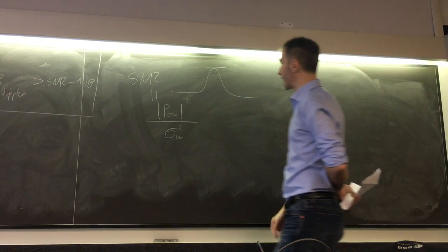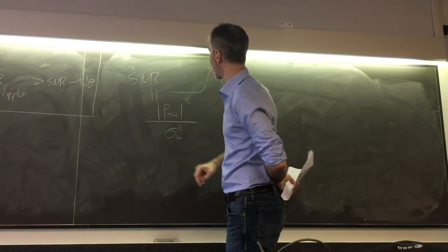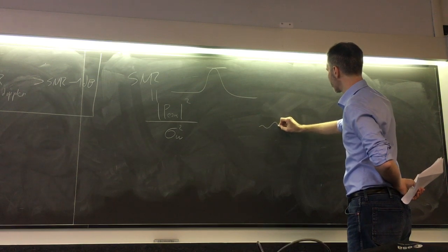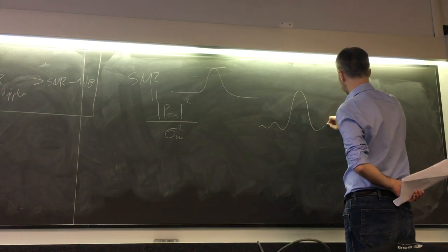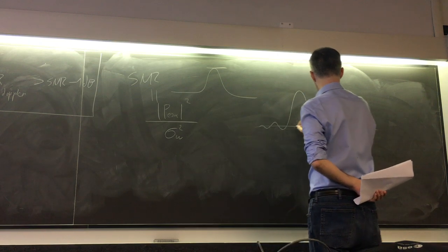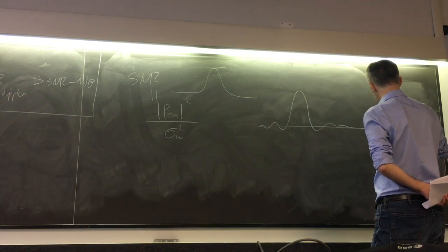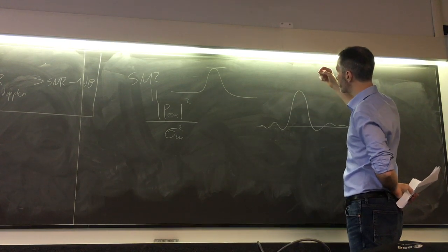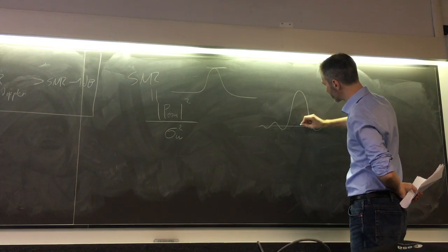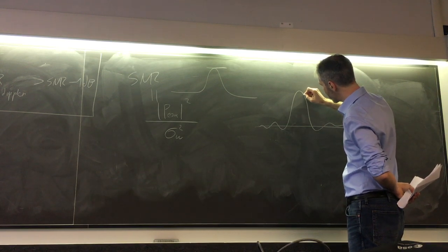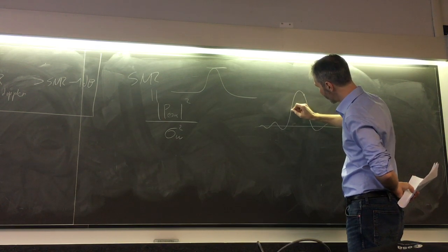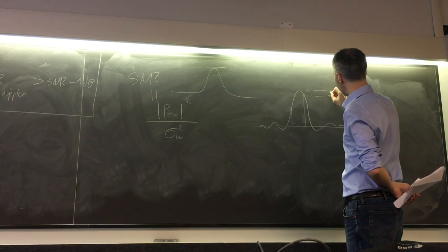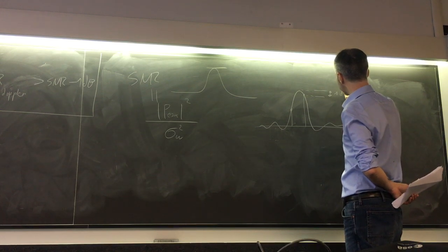And so basically this requirement is telling that if this is the cardinal sine which gives us the sensitivity of your system to Doppler, then we want to be sure that we will sample this function such that at worst we lose 1 dB from the peak.